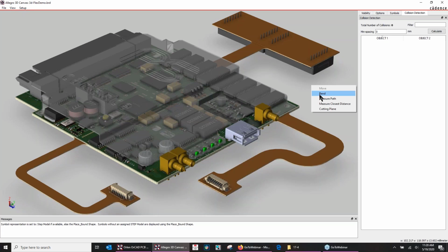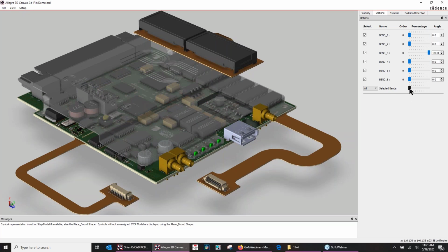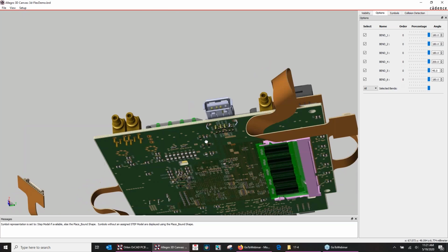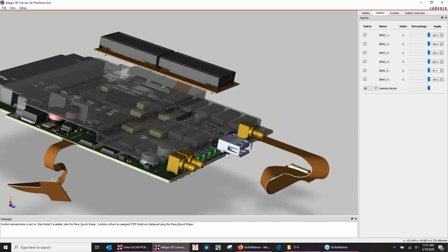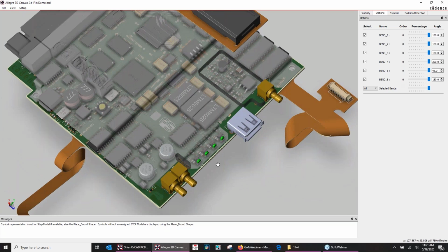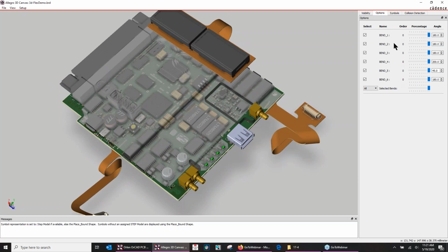And just to show you that you can bend it, I'm in Standard. Just to show you that I can bend it, let's go to the options. I'll take 3 and flip these LCDs right up there on top. And then I'll save some time and just bend everything else, all other bends in there. And what we're really wanting to show you here is the odd angles of the bends. I can export this out now and take it to my mechanical group for them to look at to make sure that the connectors are lining up after they're all bent where they should be lining up. And that's part of the bending in there.